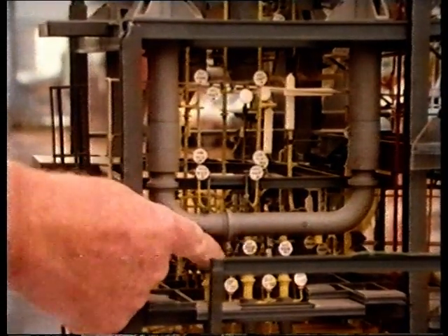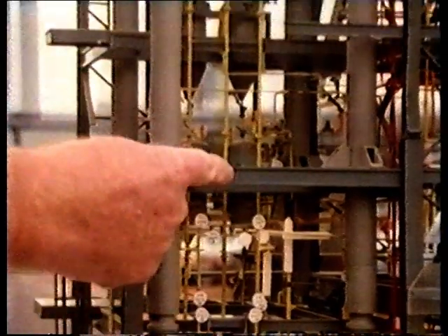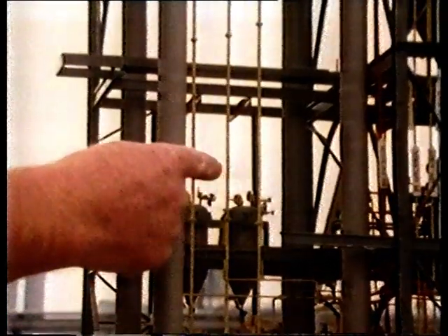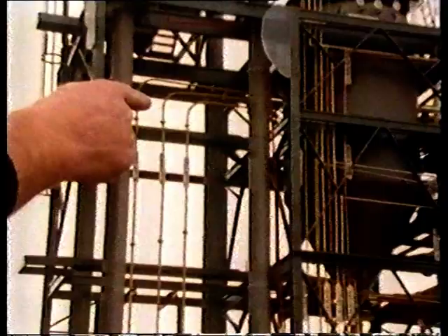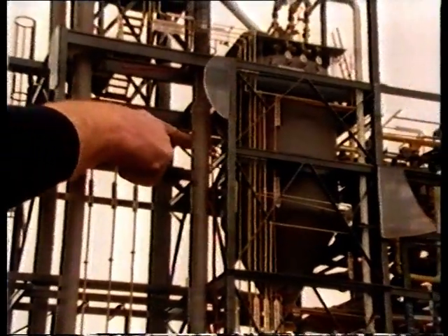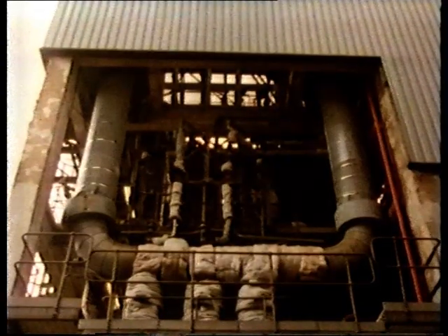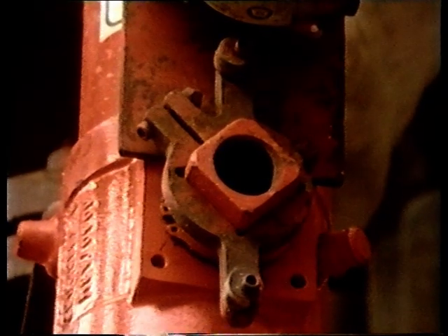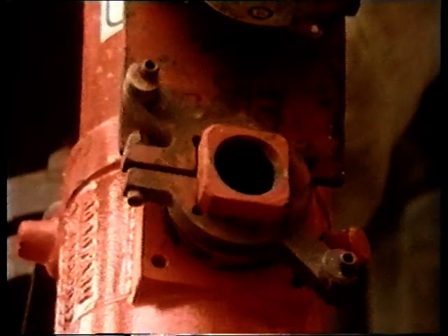On the model, here are the narrower pipes which carry the product, polyethene, and carrier up to the top of the plant. There's a tank at the top called the flash tank. As the reaction proceeds, the pressure rises in the reactor loop, and there are 3 valves which work automatically, releasing polyethene and carrier up one or other of the pipes leading up to the flash tank.